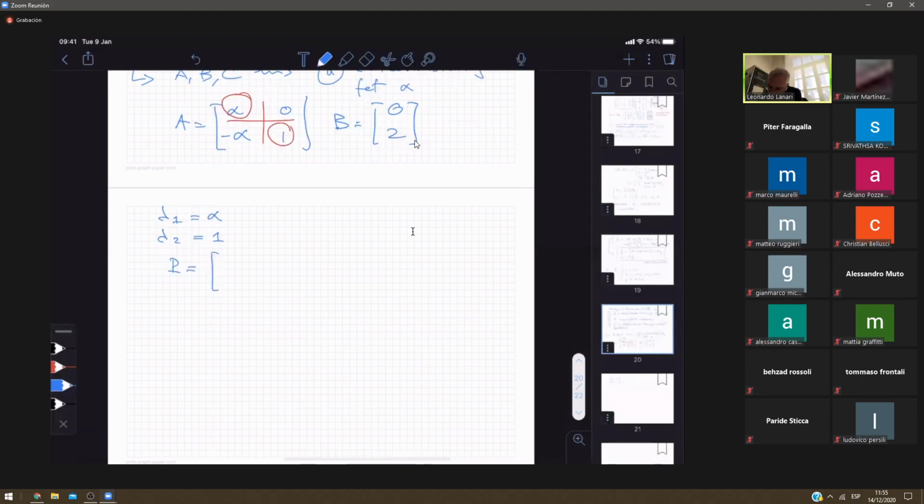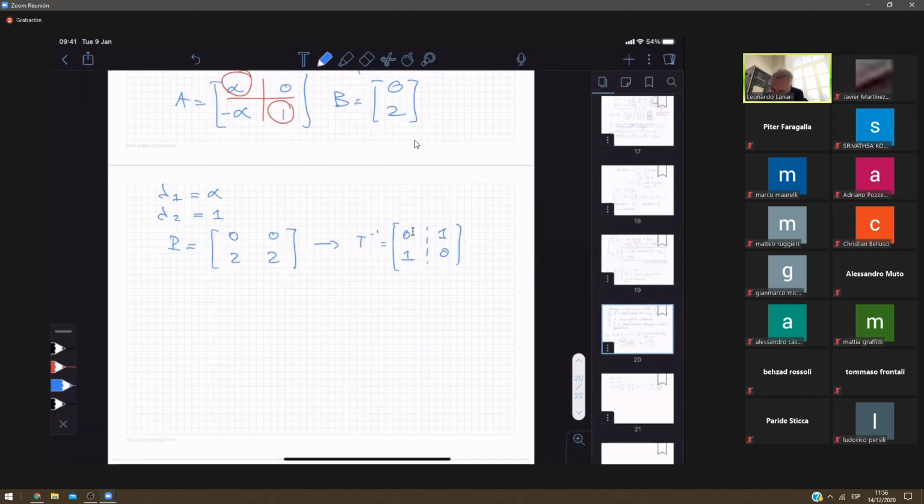Controllability 0, 2. So the system is not fully controllable. If you really want to, we can either choose a change of coordinates, so 0, 1, the base of the image, and 1, 0, completion, and then do the separation, or we could do the PBH test.